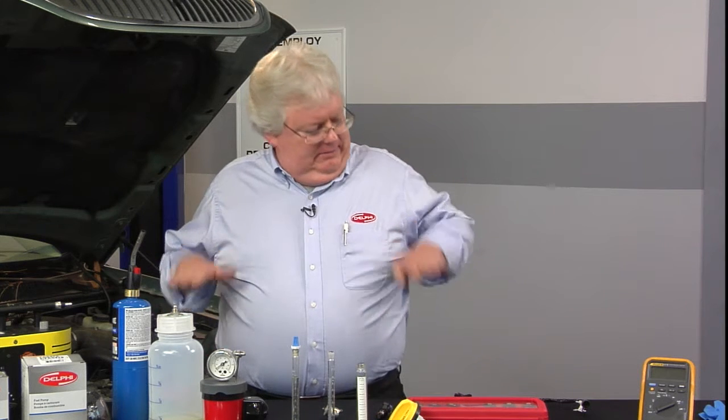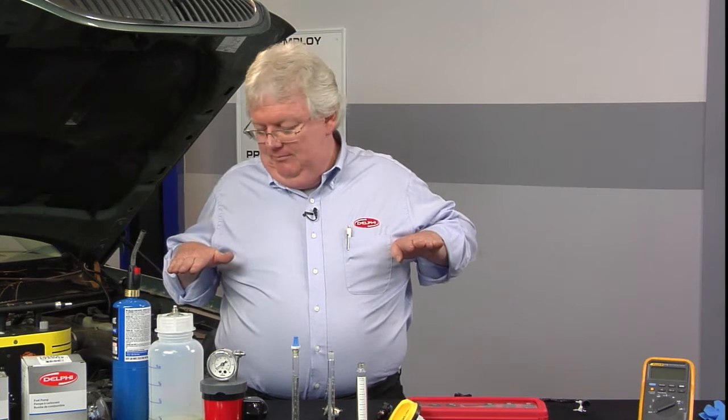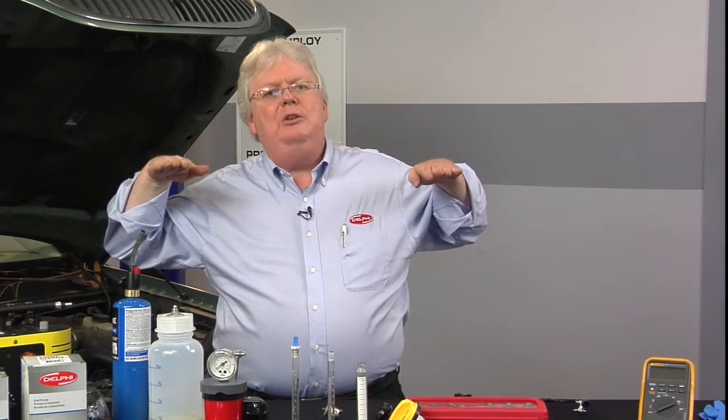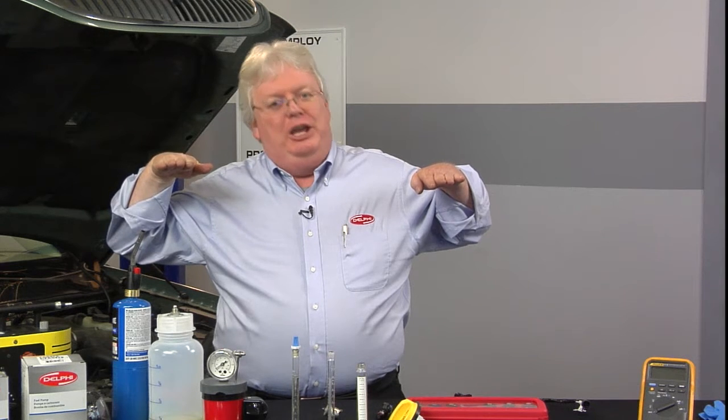You know what fuel trim does. It compensates by taking fuel away. Negative fuel trim numbers. As you see lambda and air fuel ratio, 14.7, 1 lambda, go higher than stoic or 1 lambda, 1.2 lambda, 16 to 1, then we're lean, and you know what fuel trim does. Actually adds fuel then, positive fuel trim numbers.